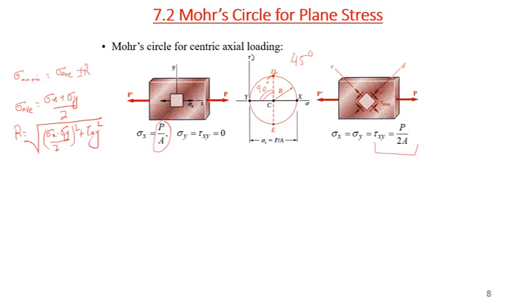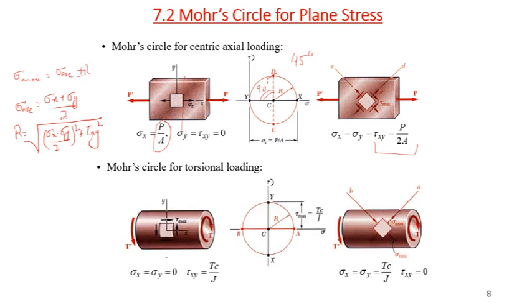And if we talk about ductile material, obviously it will break under shear. So at the 45-degree plane it will break, usually cup and cone depending on the dimension, 45 degree. But if we talk about brittle material, it breaks where you have maximum principal stress, perpendicular to the axis, and it will break from this axis where you have maximum sigma x.